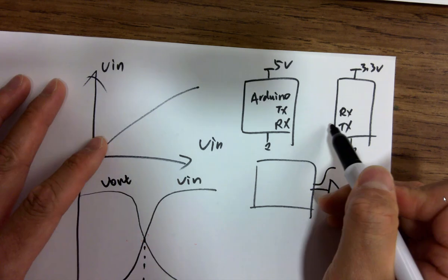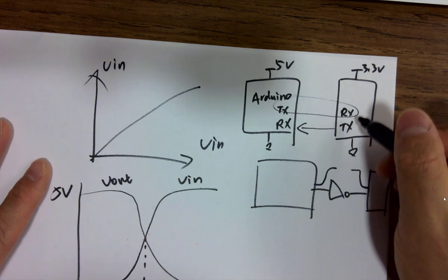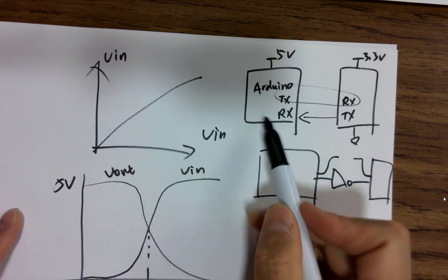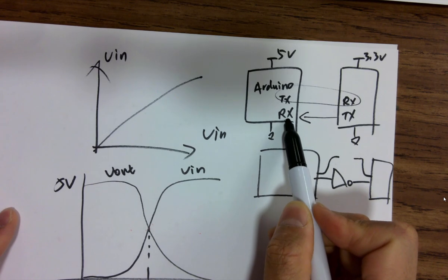So like this, right? And this is not being used. It's fine. Why? Because 3.3 volts is higher than 2.5, so it's treated as logic 1. Logic 0s are both zeros, no difference. So whenever this device is reading 3.3 volts, it reads it as a 1.